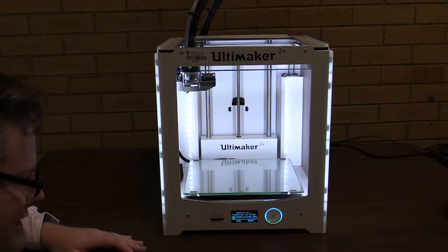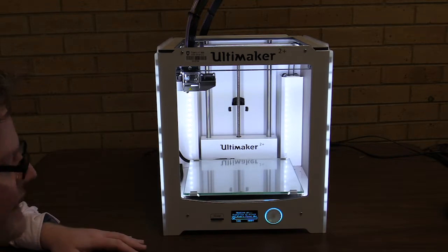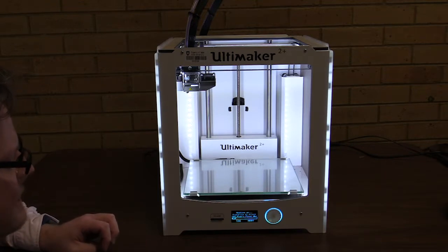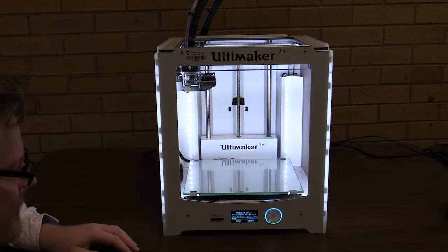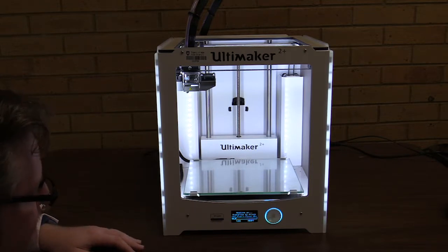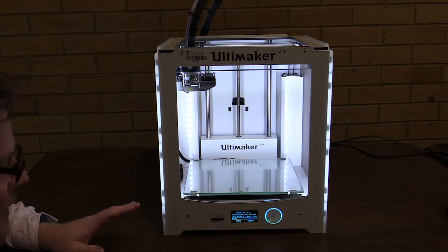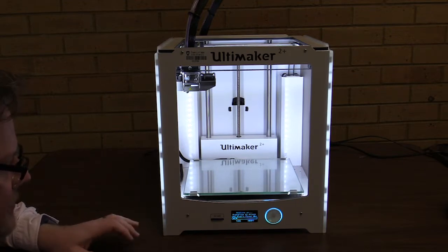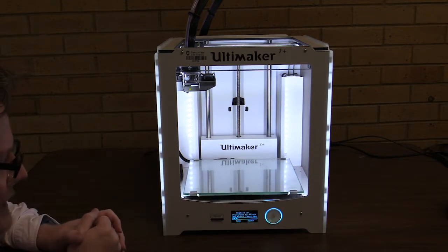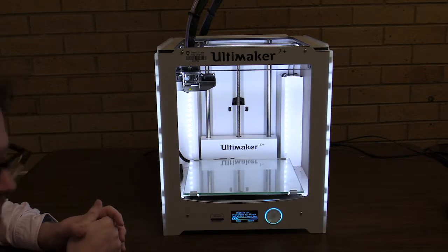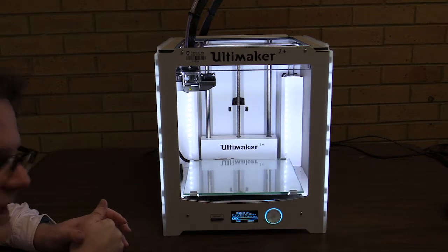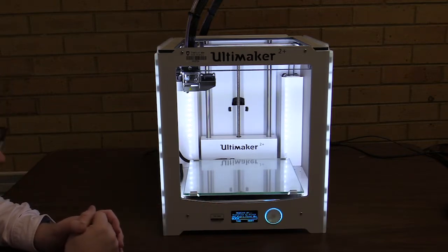You'll notice on the screen it says heating up. The print head has to get to over 100 degrees Celsius, and once it gets warm enough, the printing will start. You'll want to make sure before you start your print job that the build plate is free of any printing material and objects. So if someone may have left an object before you, you'll want to take that off before you start the printer.